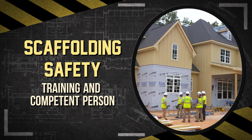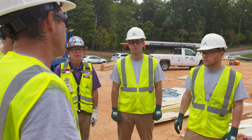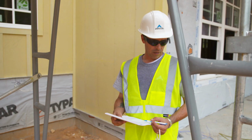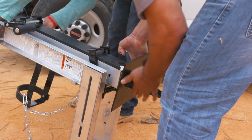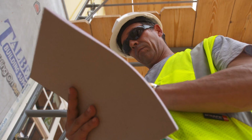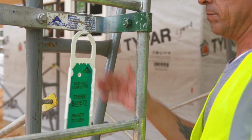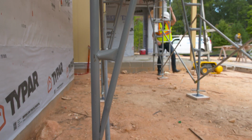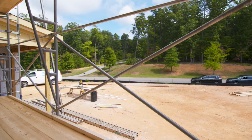Workers who are involved in using, erecting, or disassembling scaffolds must be provided training by a competent trainer who can identify scaffold hazards and has the authority to correct or eliminate them. This person should also be responsible for overseeing the setup, dismantling, or any modification of any scaffold, and is required to inspect scaffolds and scaffold components for visible defects before each work shift. By following these safety guidelines, scaffolds can provide you with an efficient work site while maintaining the well-being and protection of you and your crew.